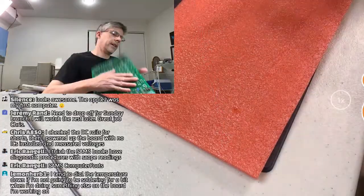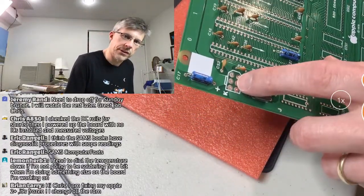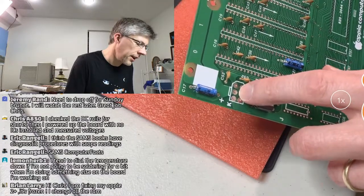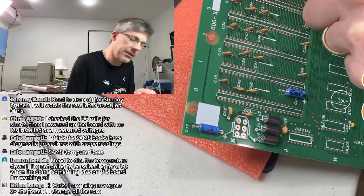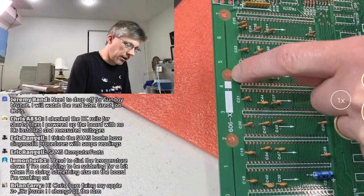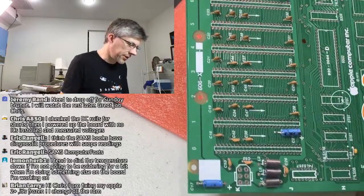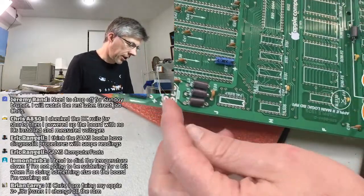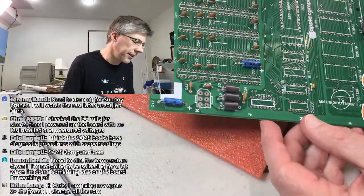You can see it goes all the way around the outside. And if you go to the front of the board, this is the plus 5 volt line here. You can see that the plus 5 volt is embedded in the PCB and runs all the way along, and you can trace where it goes to every single pin. Chris is just saying you can follow those along the sides of the boards and test for shorts that way to make sure that everything looks good.